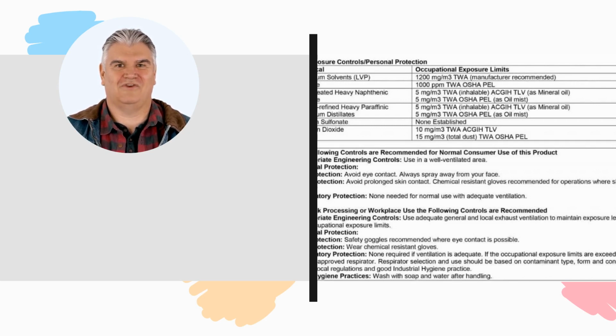Containers and chemicals shall be properly labeled. Managers or their designates shall ensure that containers of chemicals are properly labeled when received. When the manufacturer does not provide a label, the following information shall be provided on a local label. 1. Product identifier. 2. Signal word. 3. Hazard statements. 4. Pictograms. 5. Precautionary statements. 6. Name, address, and telephone number of the chemical manufacturer, importer, or other responsible party.